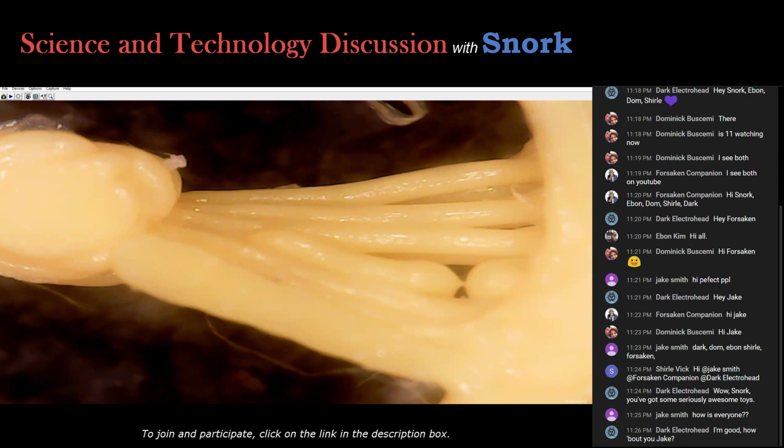So one of the material problems with 3D printing shows up right away in this close view, and that's getting the pieces of the filament to adhere to each other. If this had been something that was molded, like injection molded under high pressure, those parts would take that shape and fill quite well. So a really good mold, although you can't do everything as a mold, actually does a better job of consistent material properties. And that's one of the biggest problems with 3D printing, regardless of the material you use.